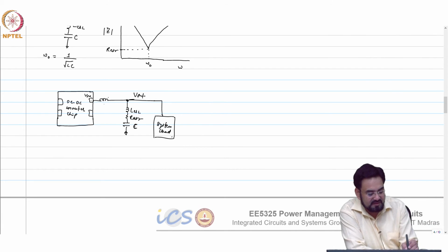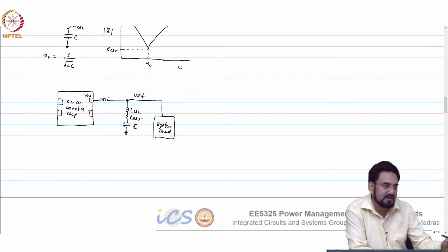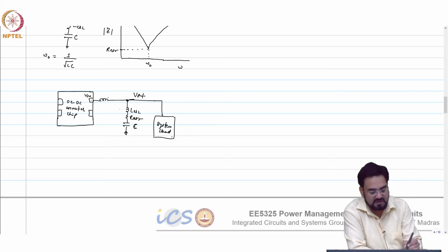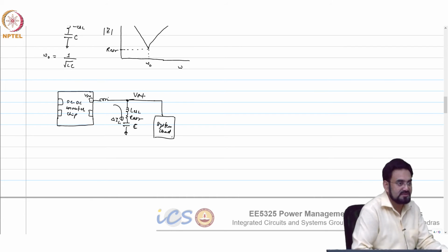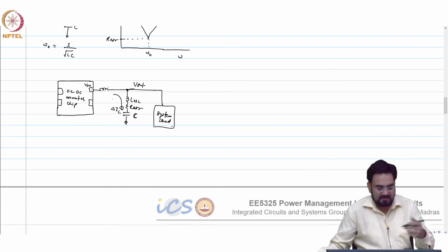Okay, so that you get an effective cap. So your inductor ripple current will go and get absorbed in the capacitor. So you don't want to have this large L in the inductor current or ripple current path. So that portion you have to minimize, because this is your delta IL which is flowing into this, and that's why we try to reduce the inductance.